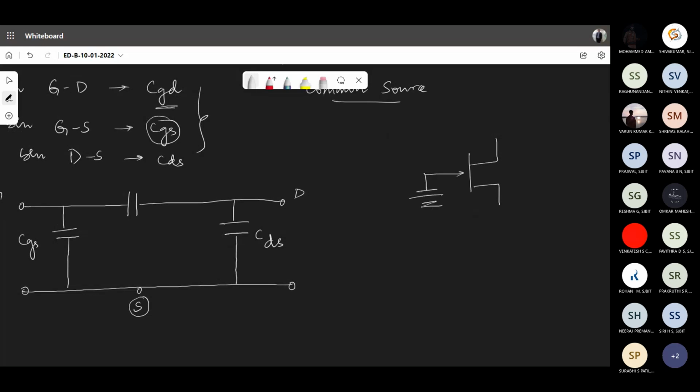So this is VGS, and what you write here is a VDS source, and this is grounded anyways. This is VDS. So when you vary this, you will vary up till 20, 30 volts. We have seen that in the laboratory also. So this is a larger value compared to VGS. VGS normally goes up till 5 volts, 6 volts like that.